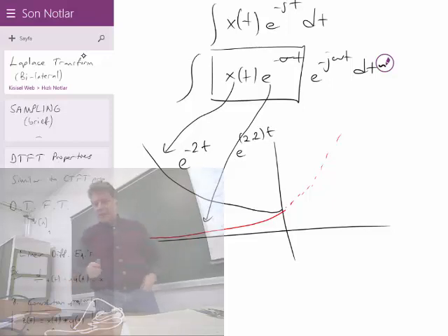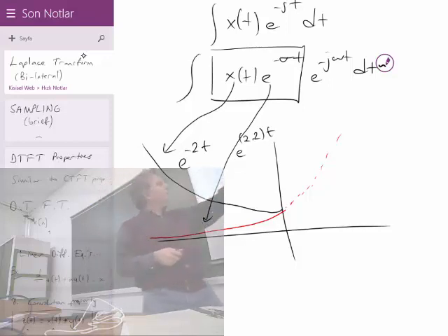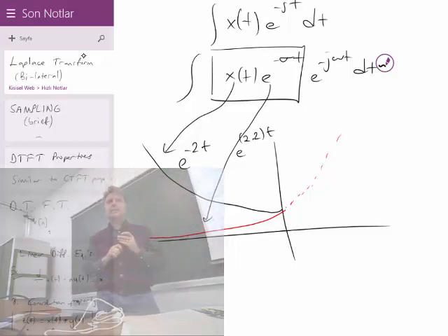So you just multiply them. And this is the trick of the Laplace transform. It artificially induces another exponential such that if your signal is going unboundedly, by multiplying with that exponential, you're trying to bound it. You're trying to make it a convergent signal. The multiplication result, the boxed term, is convergent. And you can only do it if you have some extra sigma.